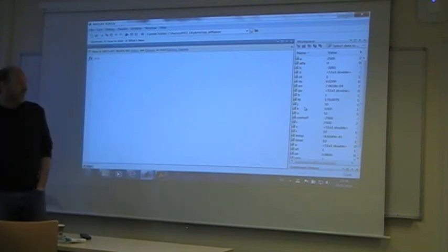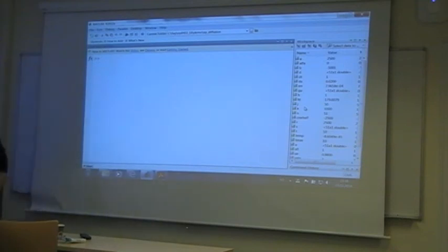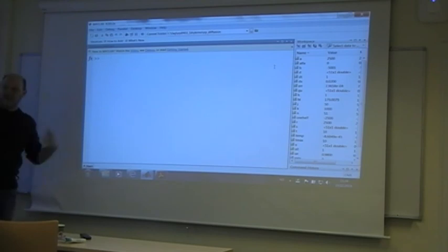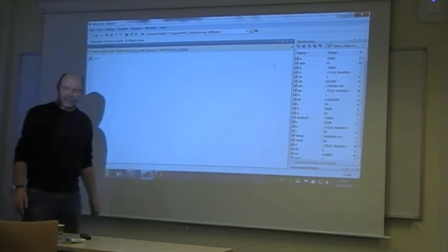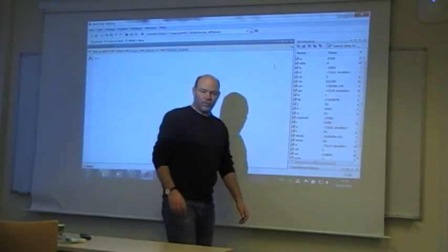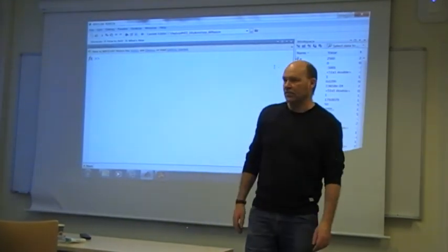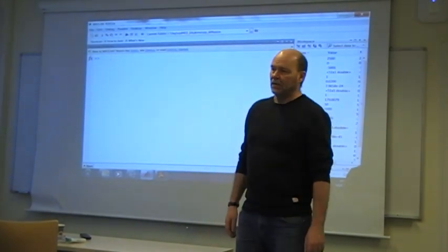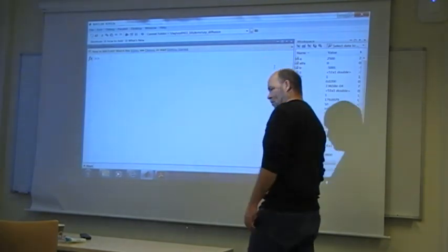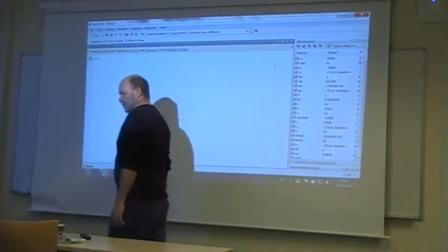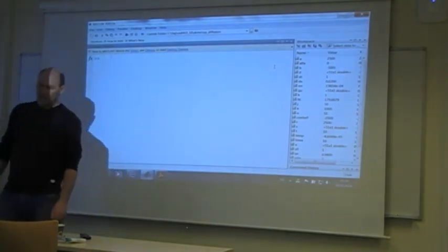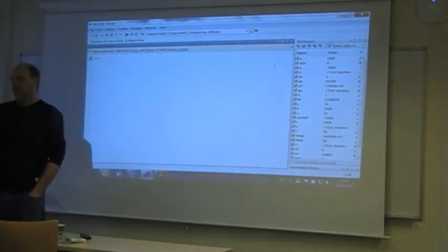And dangerously, the first codes that were sold, the first version of Fluent, you have several others as well. They typically used upwind schemes, implicit schemes, semi-implicit schemes, just to get things stable. And that meant whatever stupid things you entered into these codes, you got an answer. And the answer was 500% wrong, but you still got an answer.